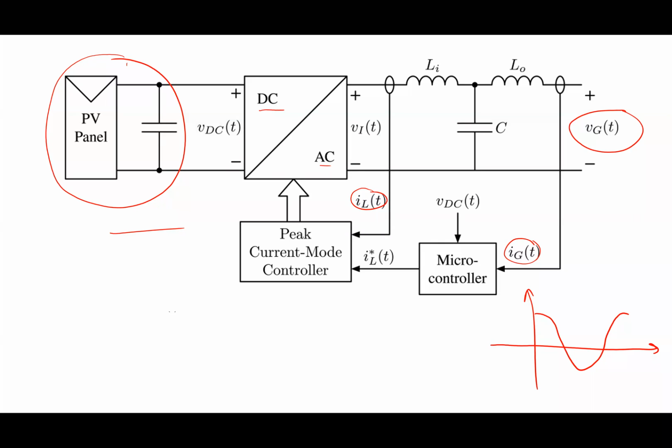Well, maybe you will. If you look on the screen there, every time I talk, what I'm looking at is called a Fourier transform. So it's going a level beyond what I'm talking about here. The x-axis there is frequency. The y-axis is the amplitude of the sine wave that exists at that frequency. So it's actually taking my voice as a voltage signal, and it's calculating the Fourier series coefficients of my voice. That's effectively what's happening.